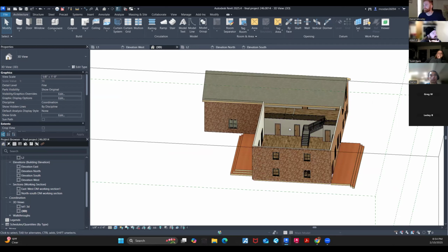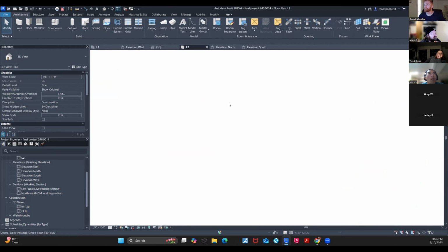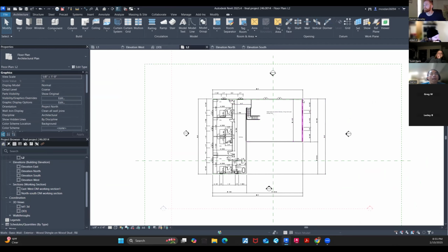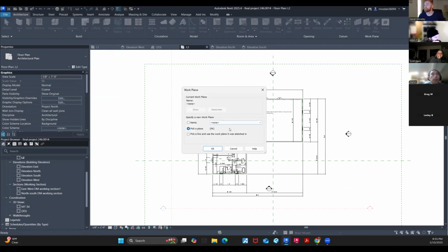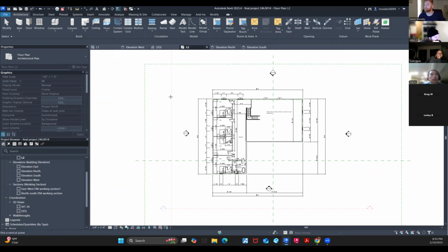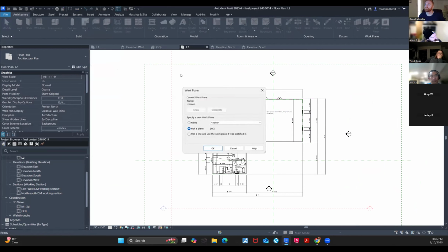Let's go now and go back to your level 2. And let's go and create a roof from extrusion. Pick plane. Let's go ahead and pick the east. Nope. Hit escape. Go back. And then let's go hit that drop down, right? And let's go choose the east wall.